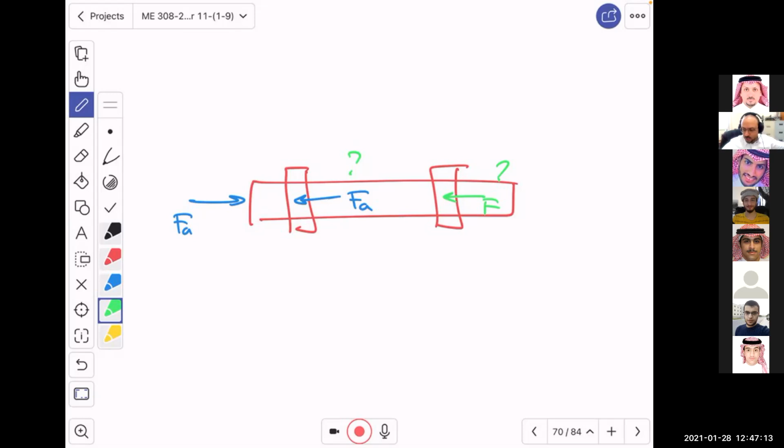Well, let's cut it short because you have only a few minutes, and then we will wish you a happy weekend. Because we didn't care. The real idea, let's assume we didn't care about axial load. We did not even calculate it. We did not include it in the design because we said that normal stress generated by bending is more dangerous than normal stress generated because of compressive load. So we didn't care.